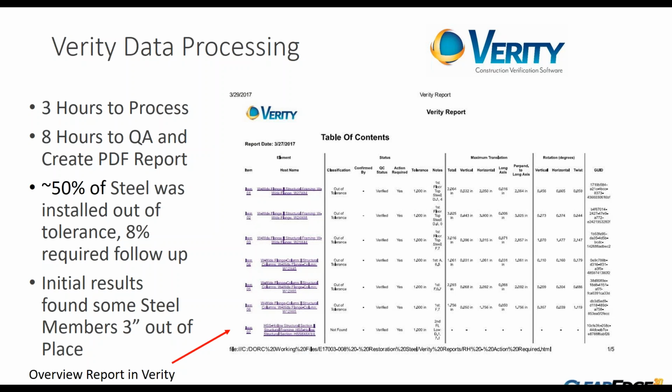For this particular project, the 73 scans, the workflow using Navisworks is exactly the same as the workflow that we used previously. We process it through RealWorks, and then we export to E57s and then bring it into Autodesk Recap. From there, we can dump it into Navisworks. So the same workflow applies, but then after we get everything aligned, it took about 3 hours to process all the